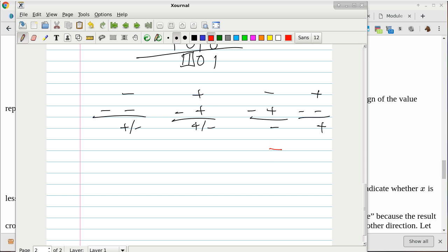So the overflow situation is this, okay? This tells me we have an overflow situation. This also tells me that I have an overflow situation. Is that okay? So I subtract a positive number from a negative number, but somehow the difference looks positive or non-negative, or I subtract a negative value from a positive value, and then somehow the difference looks negative because the sign bit is a 1. So those would be problematic.